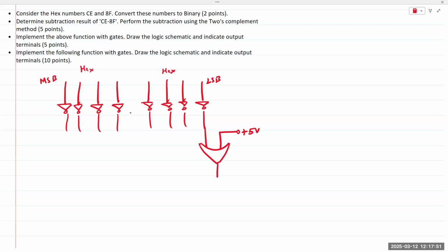If they're connected to plus 5, you're permanently, for the purposes of that circuit, connecting that to logic high, meaning 1. You're supplying 1 into that circuit. If you connect it to ground, you're supplying 0 to that circuit. So if a pin is connected to plus 5 volts, you're supplying 1. So the last digit, you add 1 to it.